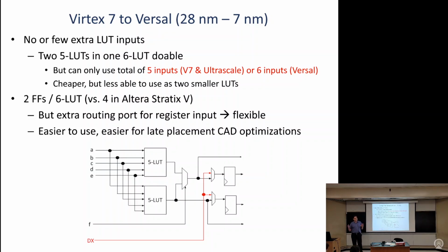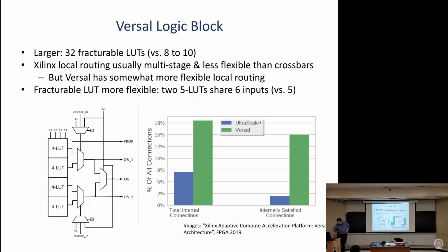And in Altera's architectures, there was a higher chance they were illegal because the whole CAD flow was built around we get to pick where the registers go, not the designer trying to put them in at the end. So for those incremental changes, the Xilinx architecture was essentially easier to understand. You put the register in and it's probably going to be fine. Yeah, so let's see.